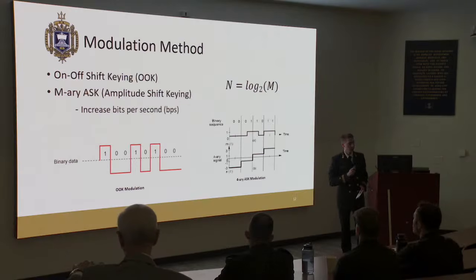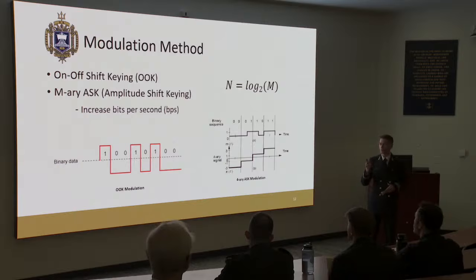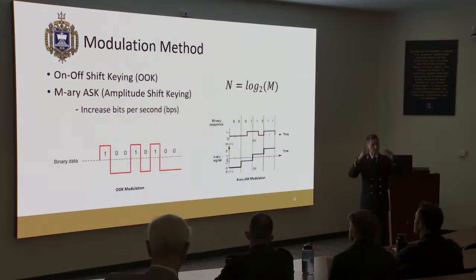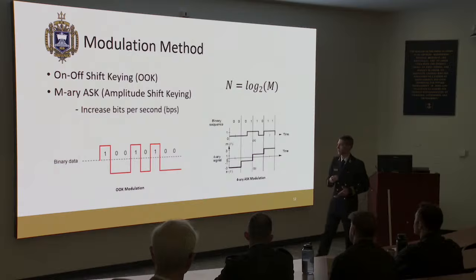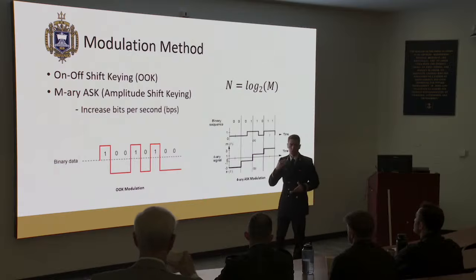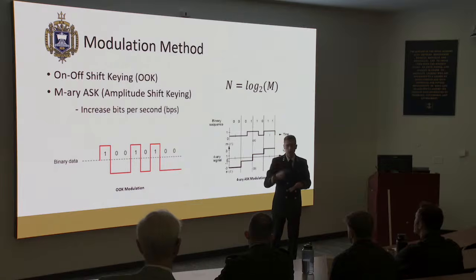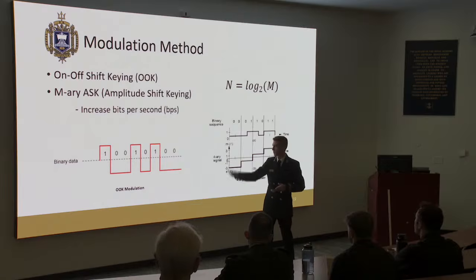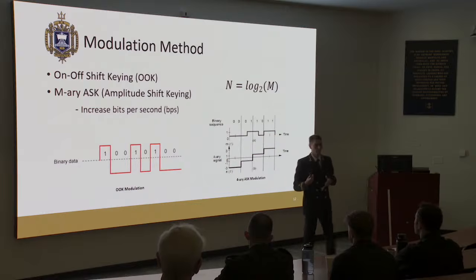Okay, starting off with developing the modulation sequence itself. As I said earlier, in order to use your laser diodes to communicate with your PV cell, you're lasing them at different power levels. Each different power level is associated with an amplitude, which can then be associated in turn with a bit, whether that be a 1 or a 0. A very simple version of this communication is on-off keying, where you only lase the laser diodes at 2 distinct power levels. Your highest power level would be associated with a 1 being transmitted, and your lowest power level being associated with a 0.